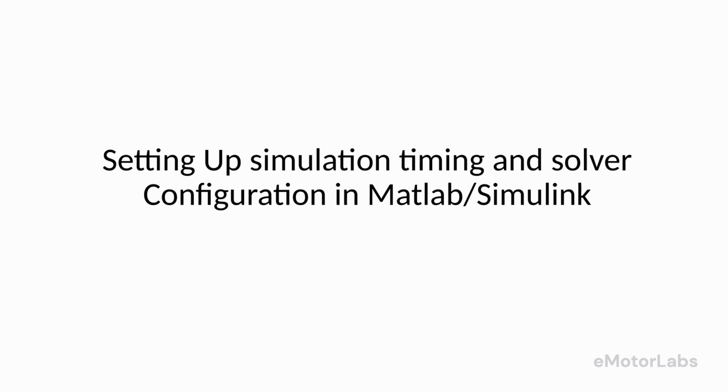In MATLAB Simulink, the timing settings determine how the model progresses through time, how accurately it captures system dynamics, and whether the results match the behavior of real digital controllers. If timing is set incorrectly, you can get unstable or unrealistic responses, choppy or discontinuous signals, controllers that behave differently from hardware, and extremely slow simulations. This is why timing is not optional, it is a core part of building reliable engineering models.